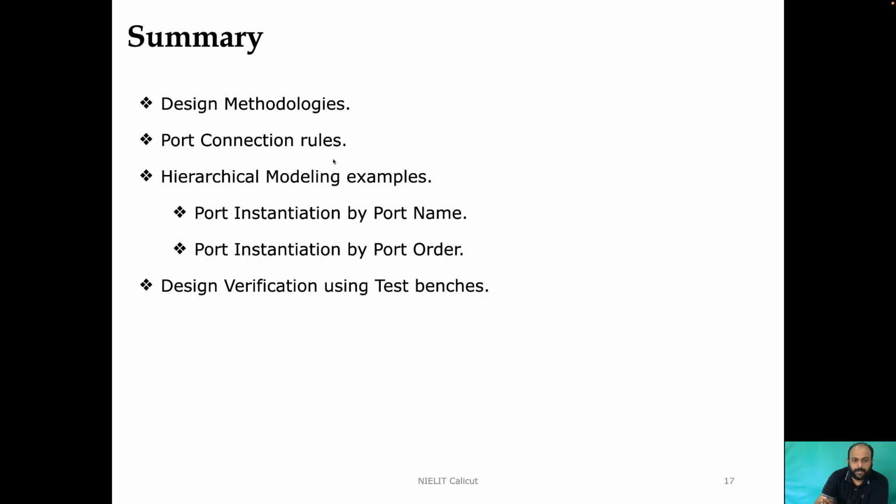We have also seen the syntax for instantiation: module instantiation by port name and module instantiation by port order. We have also seen how design verification can be done with the help of a simple test bench, borrowing the concept of hierarchical modeling. So that completes this session. Thank you.